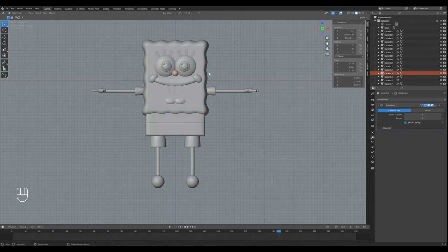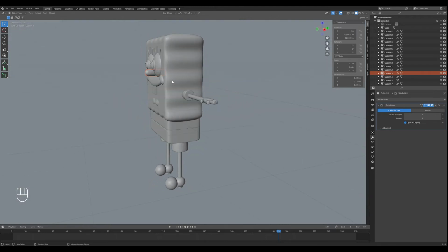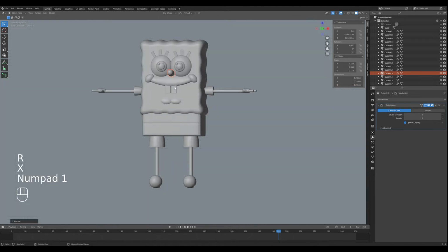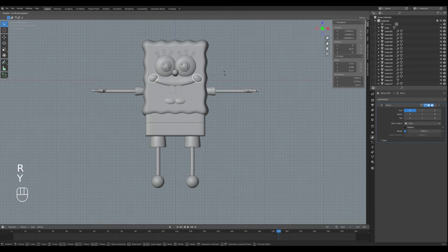Yeah, looks about right. Okay, the nose should tilt up a little bit, so you can come along to the side view here, pushing 3 on the numpad. Rotate along the X. A little better. Okay, the sides of the mouth, these circle oval things, I'm going to tilt them a little more, so rotate along the Y. Yep, along that.